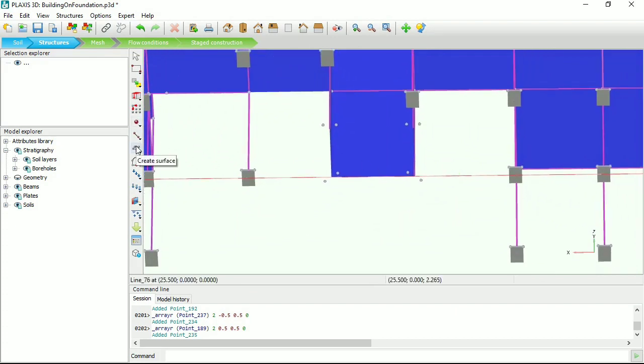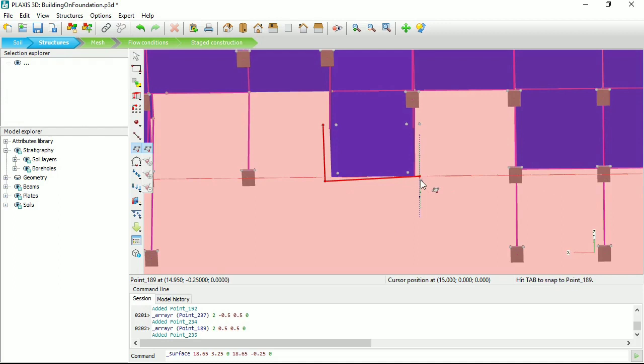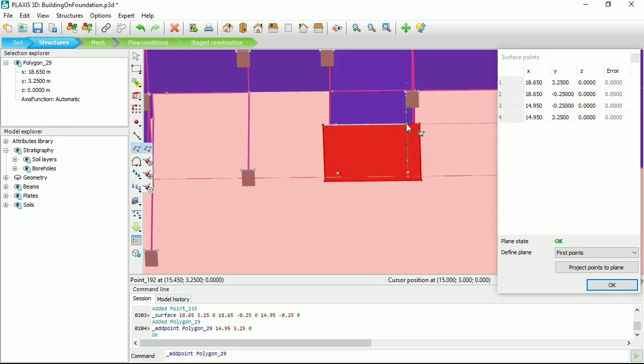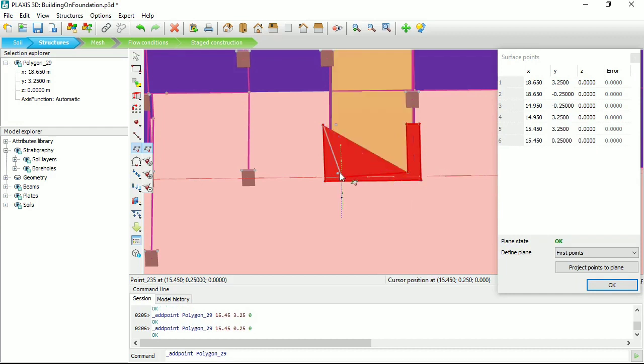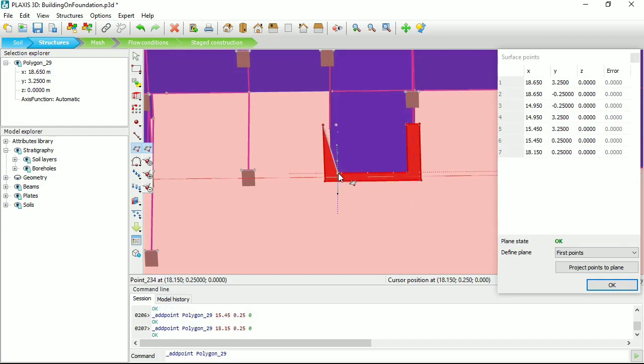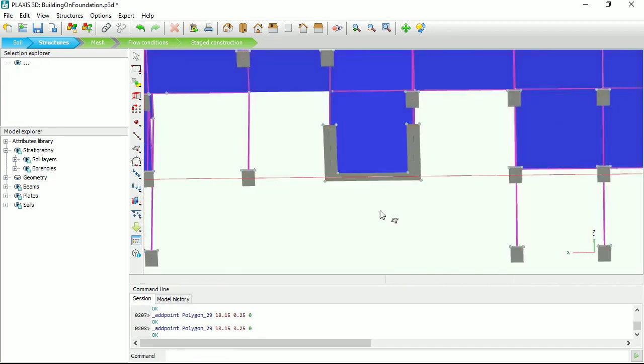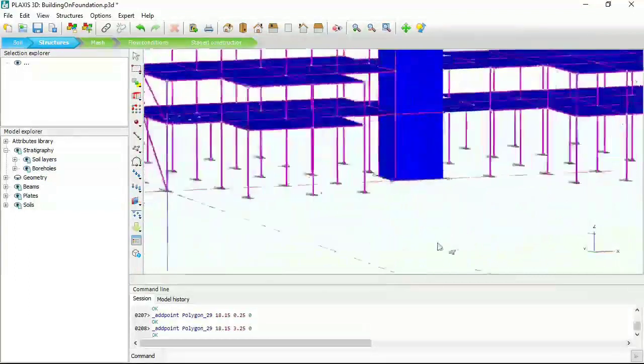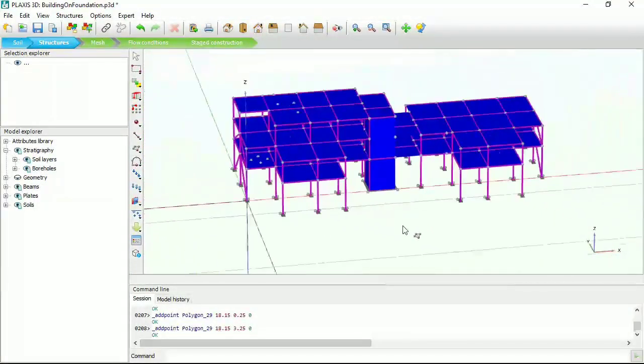And what I will do, try to highlight something I'm not sure many people know, which is creating surfaces by clicking on existing points. This feature exists from a very long time, but this is seldom used for some reason. So I figured it was maybe interesting to present it this way. So as you could see, we have all the top surfaces now properly created.